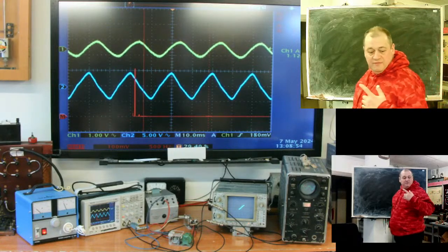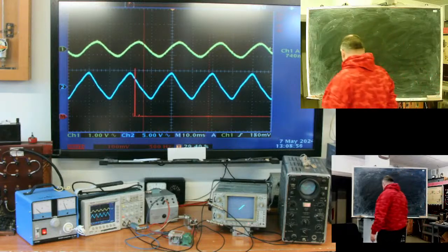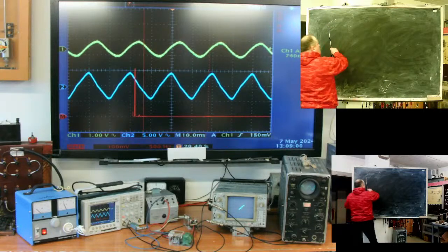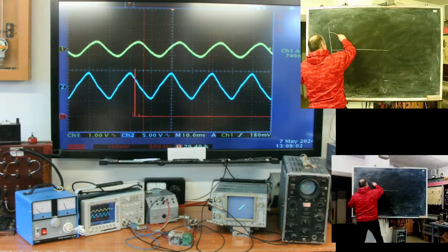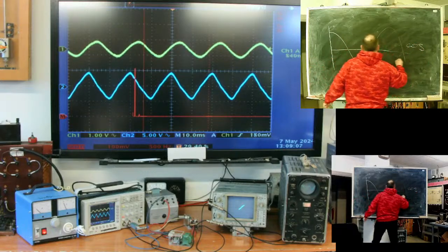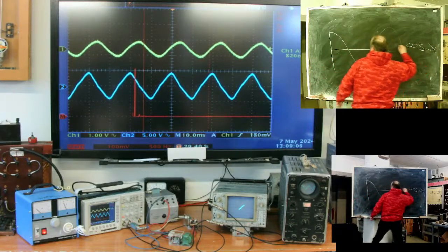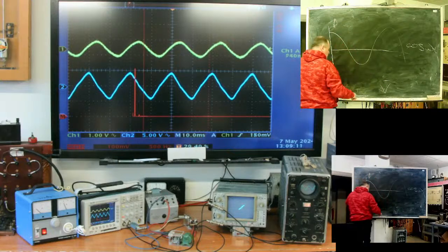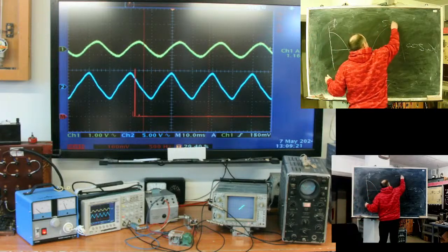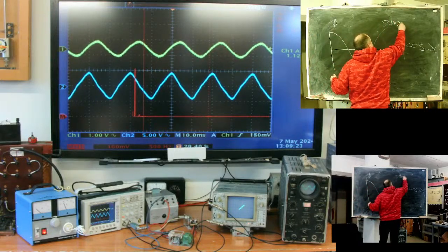At the moment when I cut the third harmonic from the magnetizing current, I had a flux like cosine omega. It was the original flux. Removing the third harmonic is like adding a flux component, with this one at 50 Hertz.